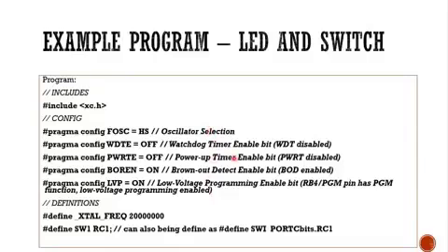The structure, as mentioned in the previous lecture, will start from setting the configuration of the compiler. You are using XC8, so the compiler must be XC8. This one you need to follow, the correct syntax, so the correct code must be the same. And then you can start with the configuration of the PIC microcontroller: frequency oscillator, watchdog, and low voltage programming.